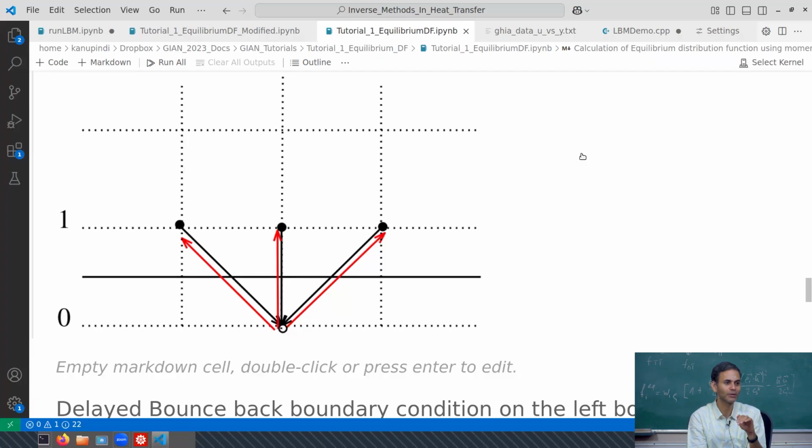Black line is actually the physical boundary, right? Because this is a dry node boundary condition, correct? So my links are stored at 0, 1, 2 and so on. Like for example, if you see here, I have drawn two sets of white lines, right? In between I have drawn the blue line, and the blue lines are the ones where actually physically my boundary is sitting. It actually doesn't correspond to any of them, because that is how the dry node formulation came about, right? If you look at the wet node formulation, then it will lie with one of them, it will lie with the outermost one, correct?